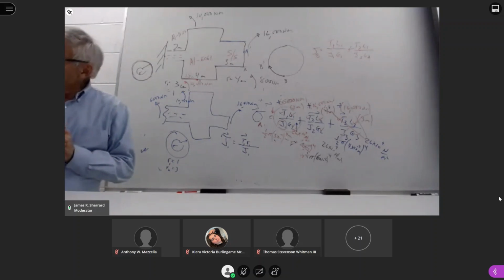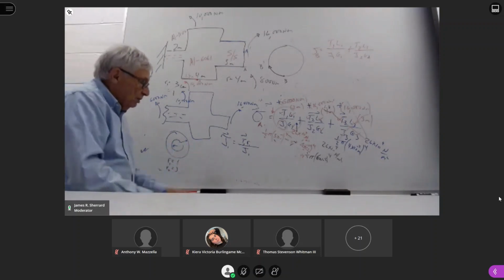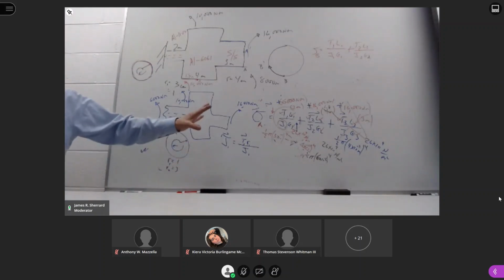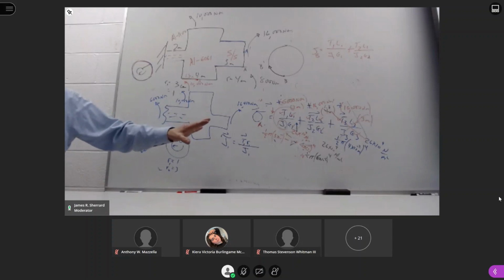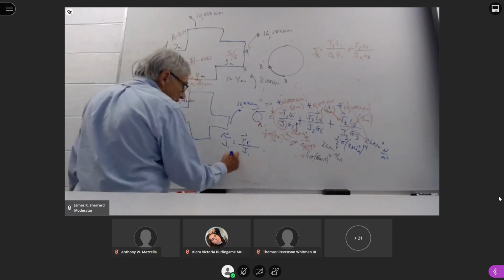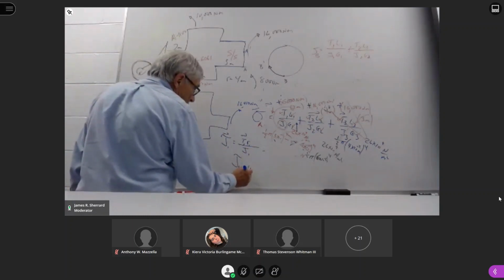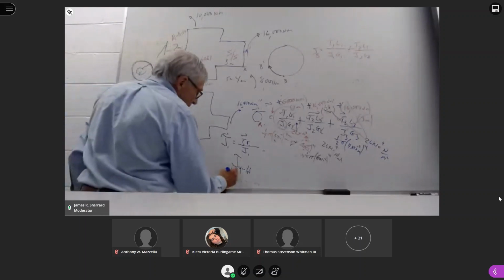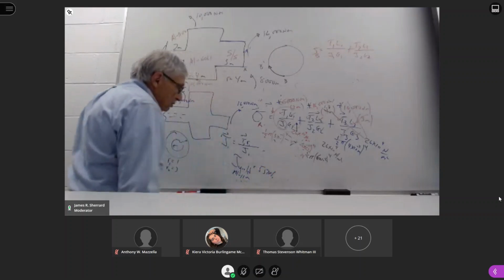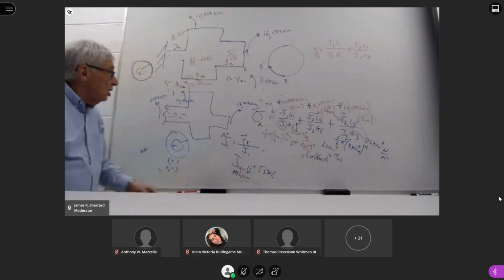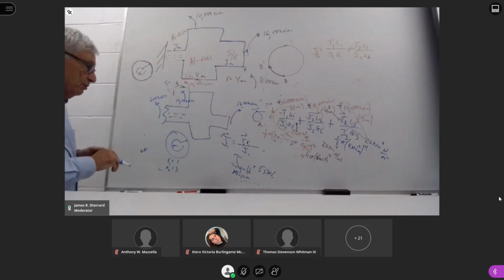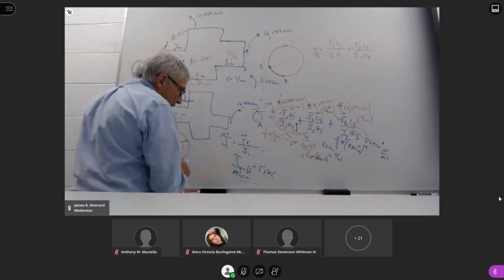And that came out to whatever this number came. Was this the one that was 143? Again, I don't have the solution. I've erased the other. We said it was unsafe before. So whatever this value comes out to be, we're going to compare it to the yield value for aluminum 1100. We know that value was 55 megapascals. Again, we know that value exceeded this, so we know it's going to fail in region 1. If we go back for safety and look at region 2, this is going to be the exact same calculation.